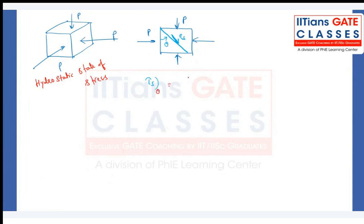We have seen this one. It is (sigma x minus sigma y) by 2 times sine 2 theta, plus tau xy cos 2 theta, with the appropriate sign. As this stress element is not subjected to any tau xy, as you can see, there is no such value called tau xy. Tau xy is 0, right?